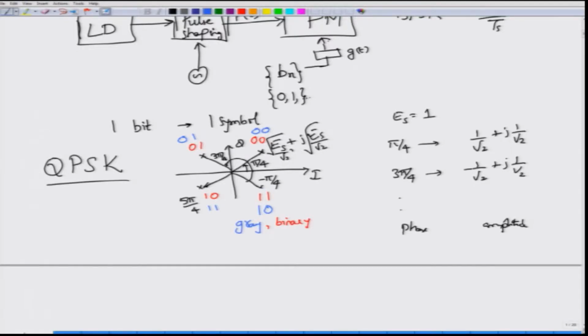So, this is the gray coded modulation, and this is the straight binary encoding formulation, right. What you have done is you had these bits with you, and the group of bits which form a symbol. Bits or symbol, both of them are equivalent, and that has been mapped onto the phase. The phase has been given by a certain value of the signal that is being carried. So, you take the bits, group them into symbols and then map these symbols onto the corresponding phase of the carrier.